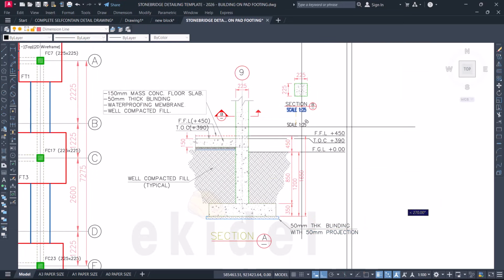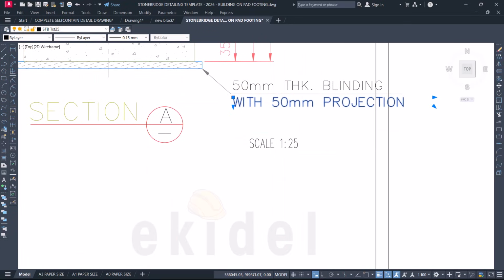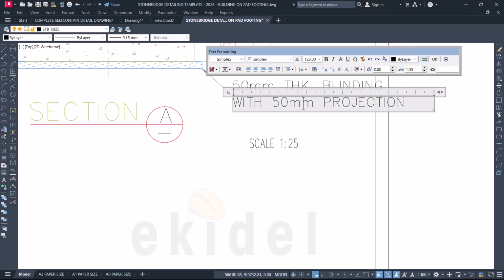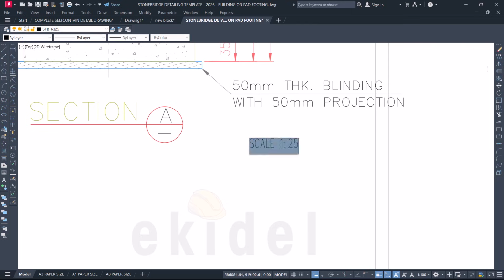Click here, copy it down here, keep this here, copy this, right? Or most times, let me see, match property, MA, if it will work, match this to this. Didn't work, yeah, because this one has a different text. So I will open here now, and then copy this, Ctrl A, Ctrl C, come here, paste this inside here. This has a different text, single text and multi-text. So that's why it will not work on the paste, on the matching.